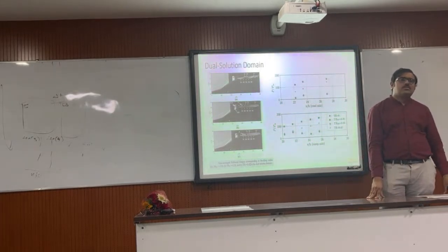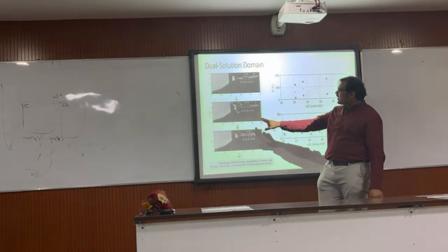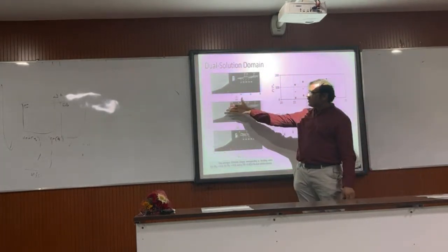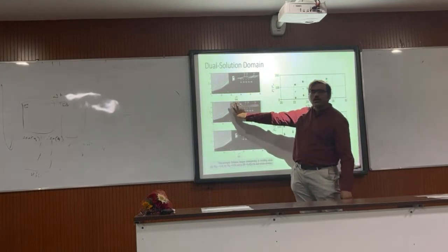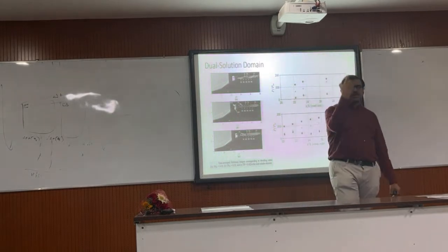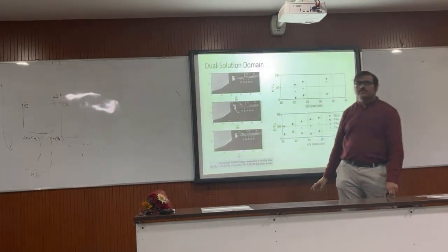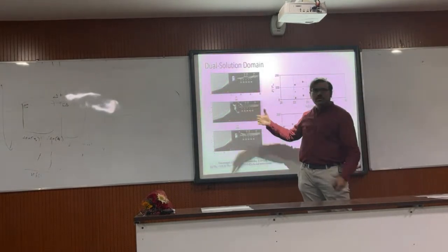How are the dynamic movements simulated, for example the cowl movement and the flaps? We have a mechanism. We actually want to see the whole intake, including the isolators. You have these two prongs, and inside these prongs there are mechanisms to move the cowl. Don't they affect the overall reading? No, they are outside, not inside.